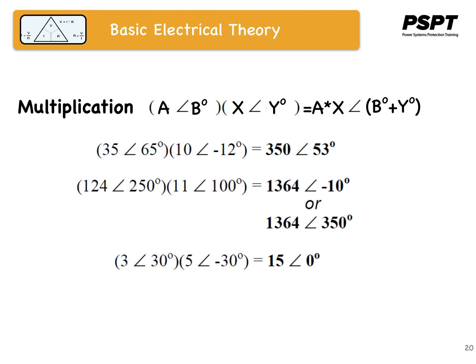So really, if you're going to be doing mathematics or arithmetic not using a calculator, which in this day and age we would, or a computer. However, when you're in the form of multiplication, you use polar notation. And when you're adding and subtracting phasors, you do it with rectangular notation. You may have to flip back and forth to make your life a little bit easier, but that's how multiplication and addition, or arithmetic, works with phasors.